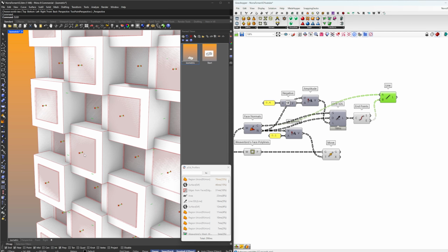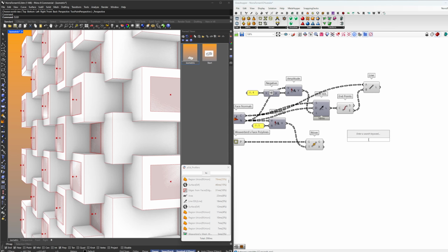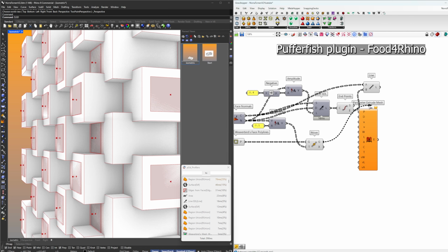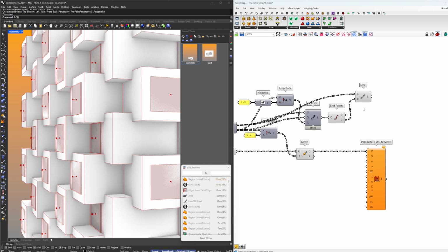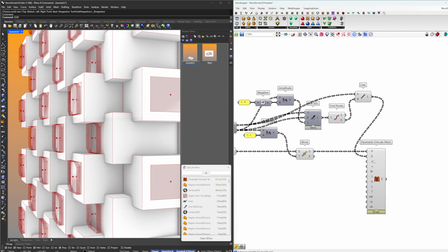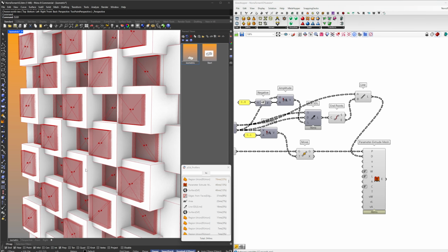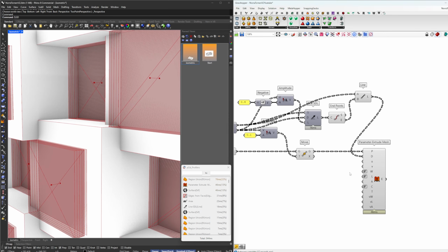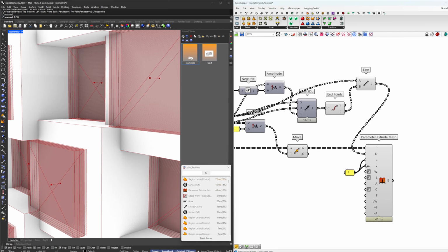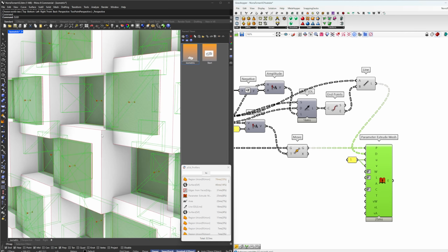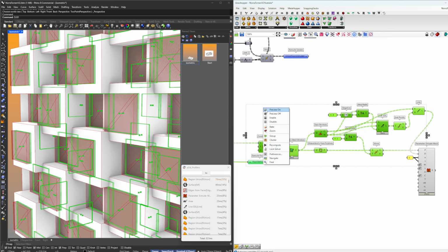So what do we have? We have created this point. Because we're going to extrude the mesh. So this curve, we're going to extrude it in this direction. This one is going to be inverted. This one is going to be this. It should be closed, as a value of 1. So, voila. We've basically created our window.